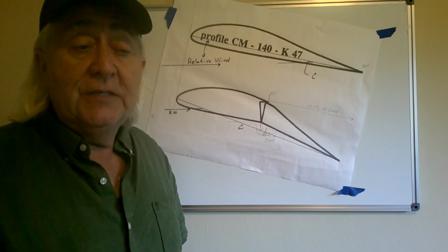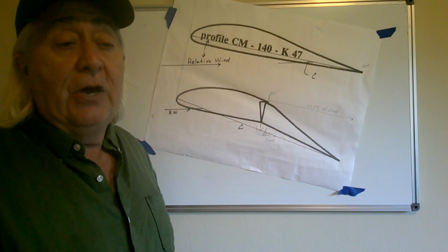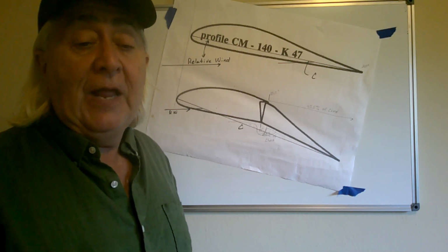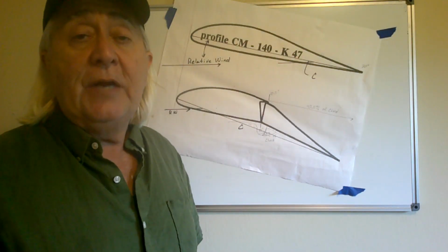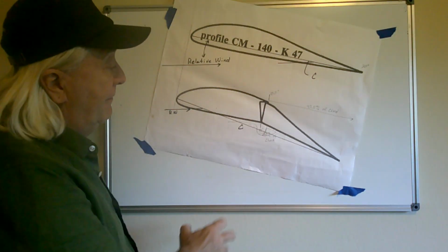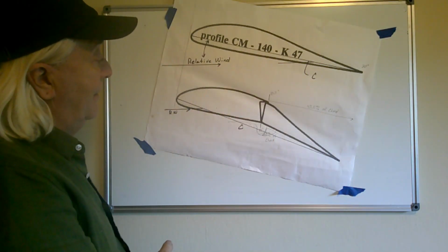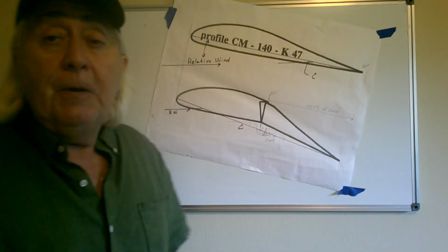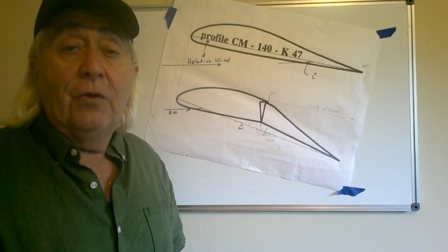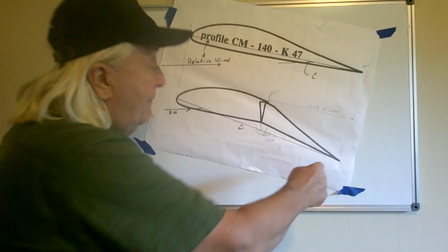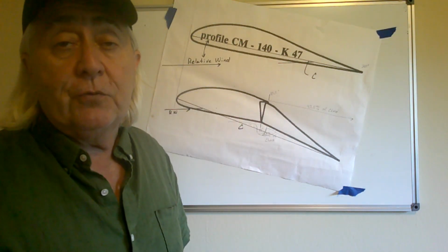Because you're flying near stall and you need to get slowed up, and you put down a little bit more flap, and boom, you go right to the stall angle of attack for this, oh, Frankenstein monster of an airfoil that happens when you hinge it halfway. So, bottom line on the whole thing is, don't hinge control surfaces forward of about 30% of chord.